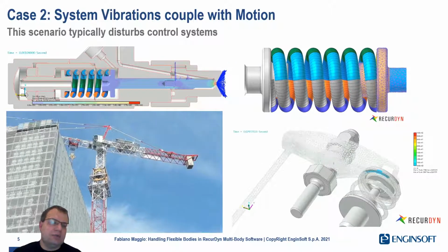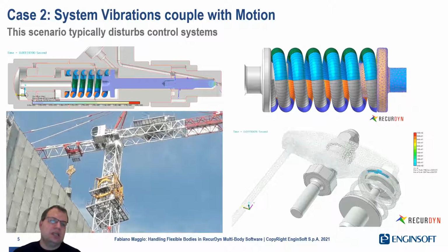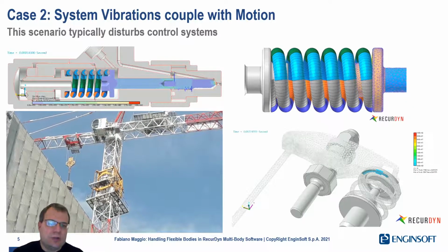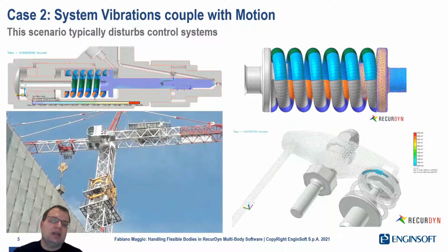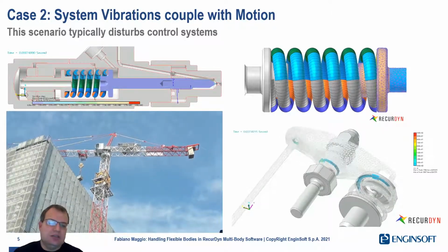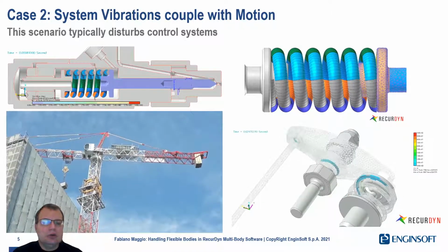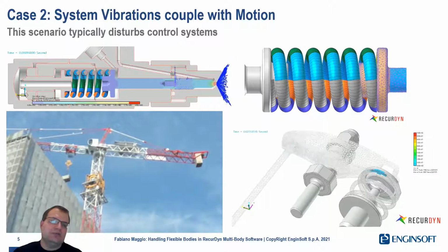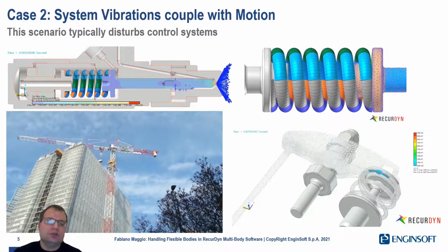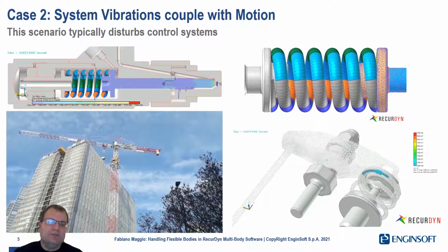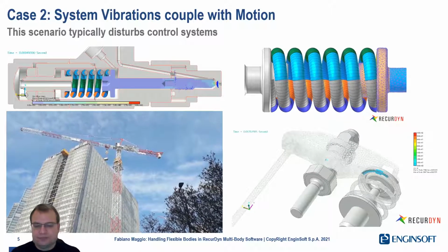The fourth example is a valve train. We will see it later in a better way. In this case, we have again a fast dynamics like the injector, and you need to include a full flex model for the spring if you want to predict correctly the valve lift.